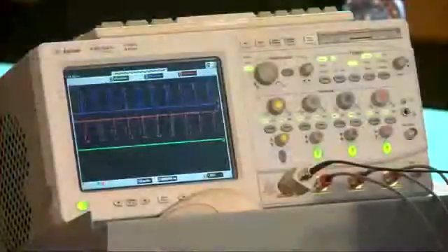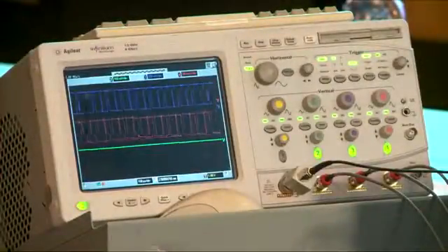So I can take the signal here, drag it to the PWM output, and this is what we get on the scope directly. So I have the model that is running in real time. The model was already running. And I simply said, okay, now I want to have this output from this model connected to output number 1 of the simulator here. And this is what we have on the scope right now.